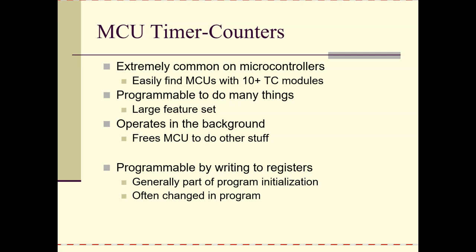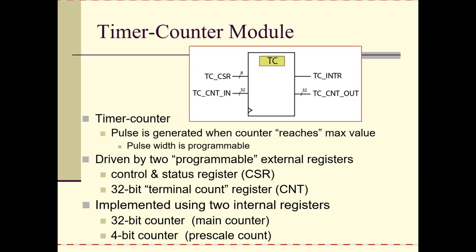These are devices that are programmable via registers. They're not executing code, but you program a control and status register such that the register controls the timer counter in the way you want it. Very flexible. Even our simple one in this experiment is quite flexible, but nothing like what you find on a real microcontroller. So this is our timer counter module.